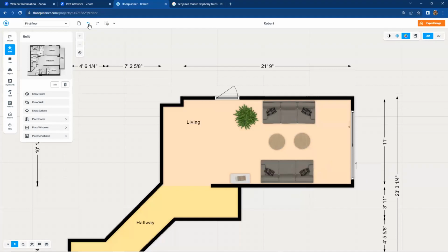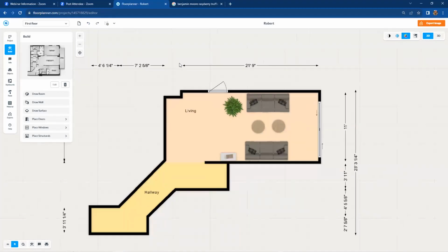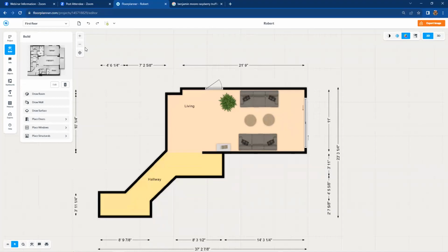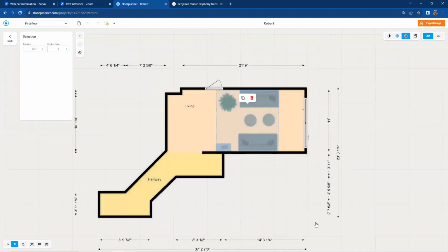I'll use my undo button to put it back the way it was. If I hold my shift key and left mouse click and select a window over the entire project, you would think it's going to pick the walls and the structure also, but it doesn't. It will always select on the first pass just the furniture and the fixtures in the room, which would be your baseboards, light fixtures, appliances, etc. With all those items selected, again, I can rotate them, copy them, move them, etc.